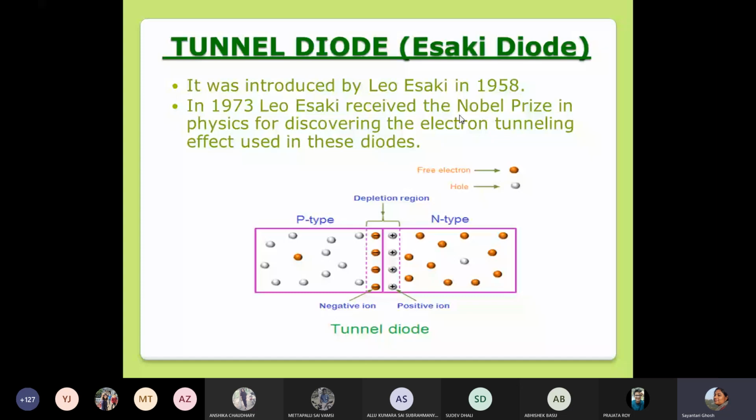So how is this device different from the usual diodes that we have? Almost nowhere. It is basically a p-n junction: just a p-type and an n-type fused together, exactly like the p-n junctions you have already studied in detail. You have studied its band structure and depletion regions; you have become experts at these things by now. But the only difference in the case of the tunnel diode is that both the p-type side and the n-type side are really highly doped.